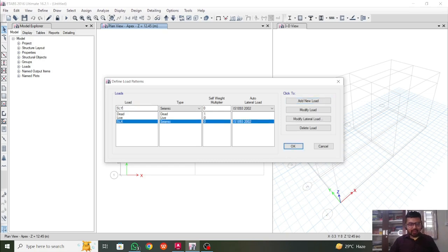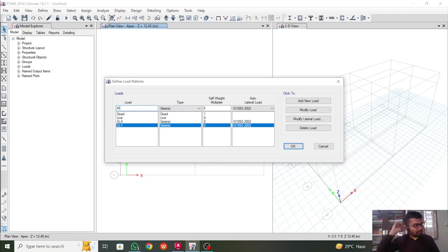Instead it is Z direction. In ETABS it is Y direction. You can see these coordinates are interchanged. This same coordinate system you find in AutoCAD and in ETABS, but in STAAD, Y and Z are interchanged by default. Actually you can change that in STAAD also. Okay, so X and Y here, and then we want to add the wind load.